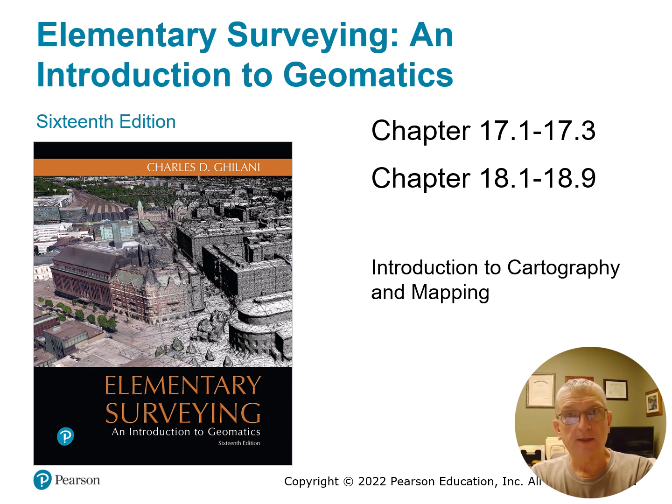Thankfully, in the era we're in, GIS, or Geographic Information Science, typically using the ArcGIS platform, does a very similar, nice, wonderful, modern job of creating maps and map features and being able to use layer controls and other niceties. And just to touch on GIS for a quick minute, the main difference between a GIS map and a survey map is metadata. You can actually draw a high precision survey in GIS mapping software. It's just pretty clumsy for that purpose.